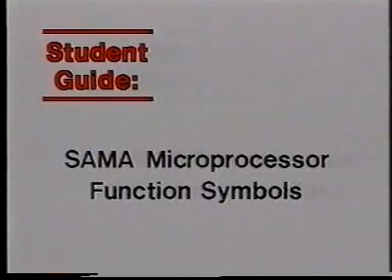SAMA also provides a number of signal processing symbols which indicate the action programmed into the microprocessor. These are included in your student guide. Familiarization with these will make the functional diagramming of a process much easier to understand. Let's look at some examples of how SAMA symbology works.